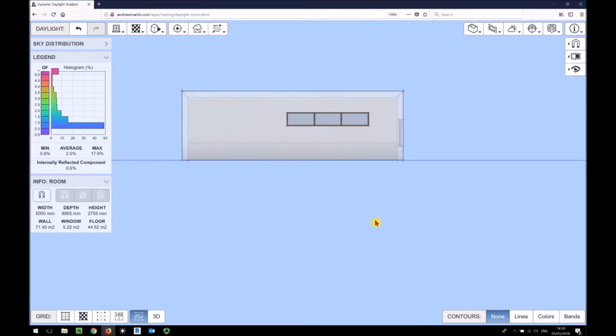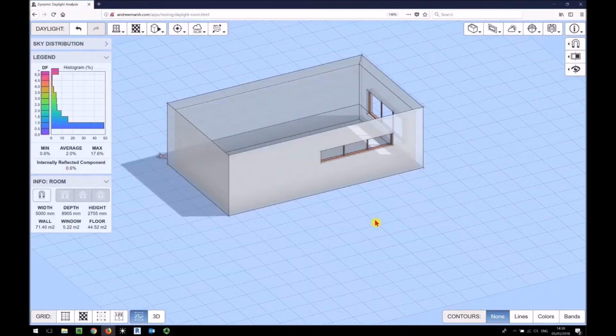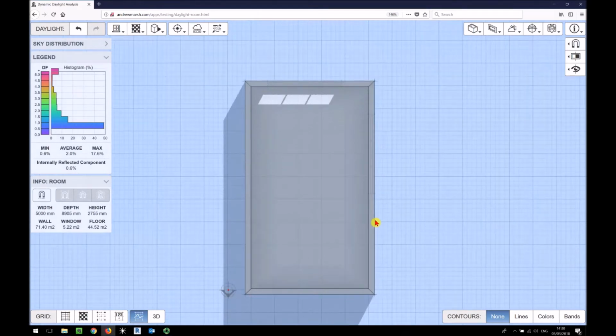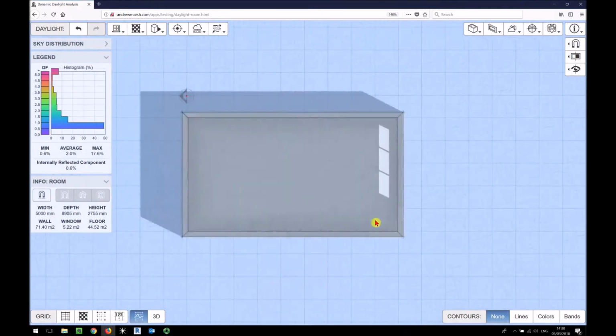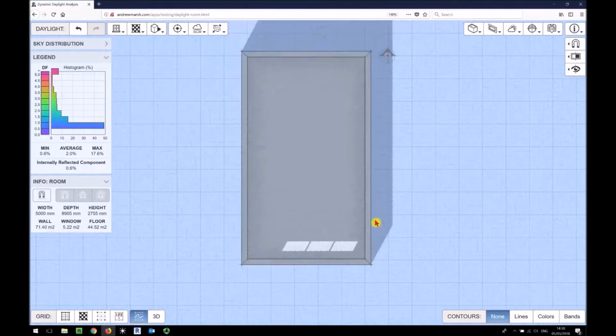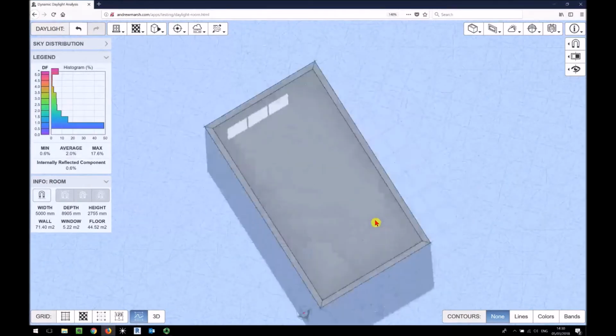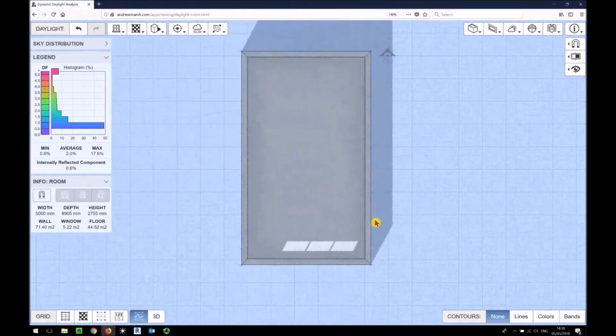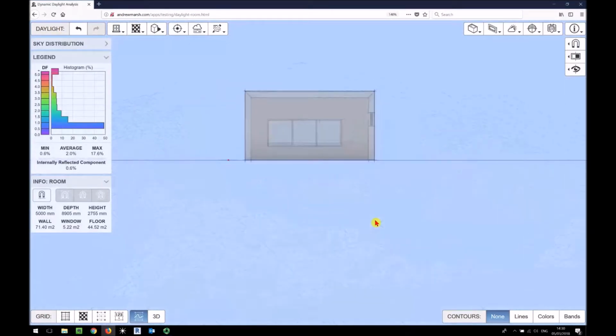the other side view. The interesting thing is if I press number 3, so that's plan view, if I press number 3 again, it rotates by 90 degrees, press it again, so I can keep on rotating, cycling around the different options of that 3D view. Same thing with the side views. If I press 4 and then 4, I get the 2 sides from that particular view. Again, the 2 sides from the other view.